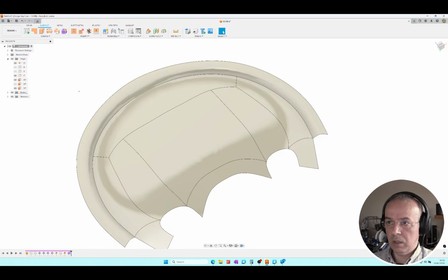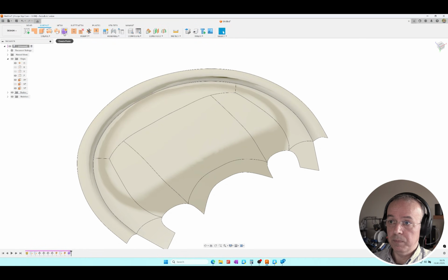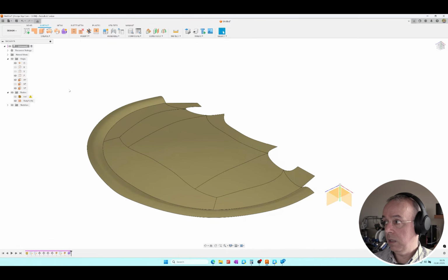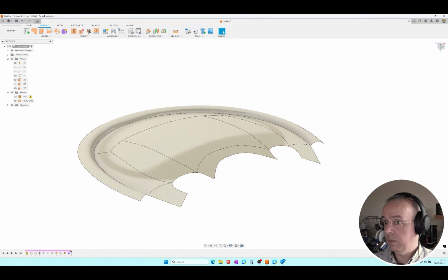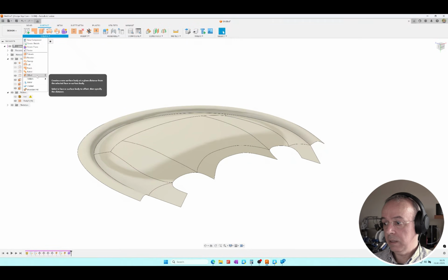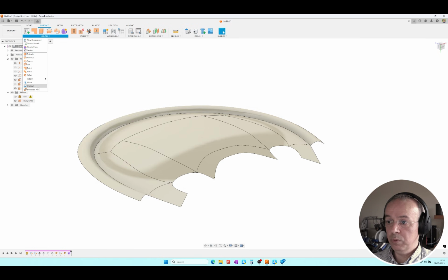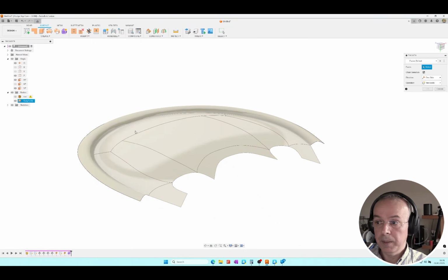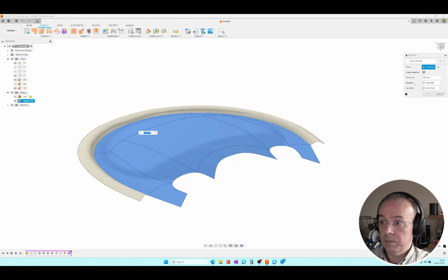The T-spline created with this command has just been converted into a surface. Yes, now it's a surface, which means we've entered another domain. The domain of surfaces equipped with extremely powerful tools. Once you have a surface, it's quite easy to turn it into a solid. One way to do this is by using the Thicken command. This command is available here, and if you now assign a thickness to this object, let's say 1mm, it will effectively generate that thickness.